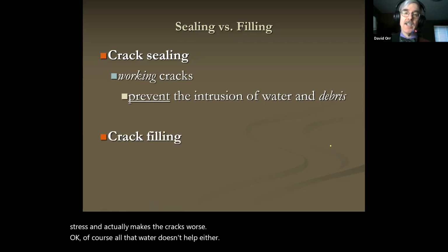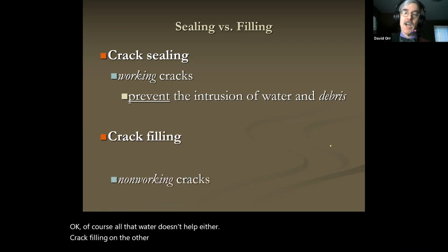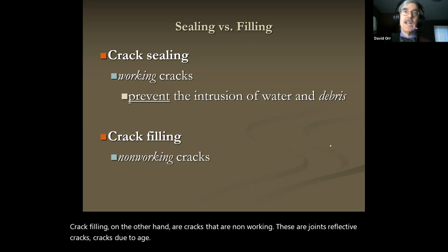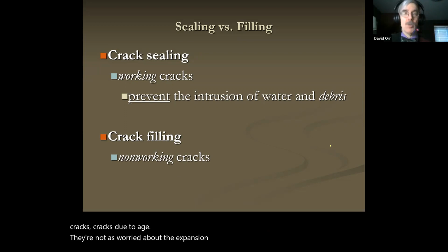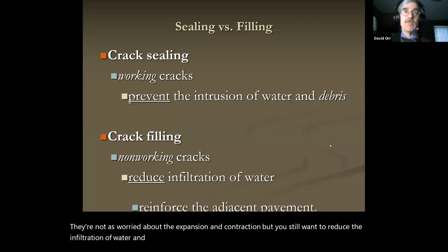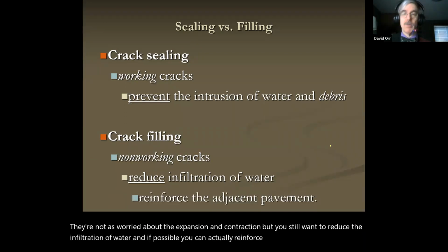Crack filling, on the other hand, are cracks that are non-working. These are joints, reflective cracks, cracks due to age. They're not as worried about the expansion and contraction, but you still want to reduce the infiltration of water. And if possible, you can actually reinforce the adjacent pavement a little bit.